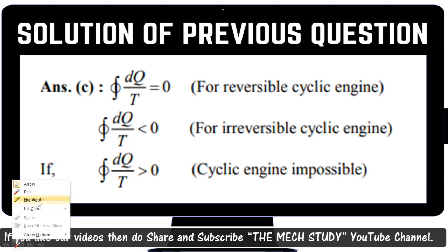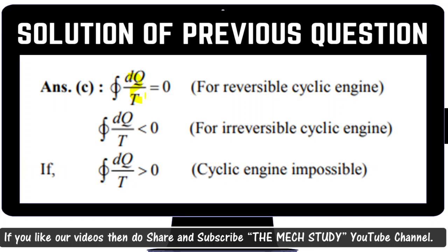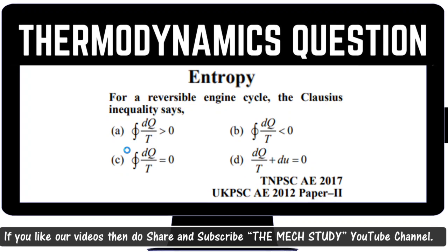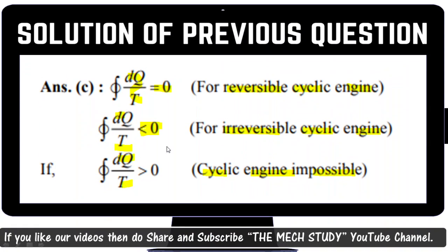There are 3 conditions for the Clausius inequality. When the integral of dQ by T equals 0, then this type of cycle is a reversible cycle engine. If dQ by T is less than 0, in such a case the cycle is an irreversible cycle engine. If dQ by T is greater than 0, then this type of cycle is considered an impossible cycle. These are the 3 conditions. Based on the condition, you need to mark option C, which they have already mentioned in the question.